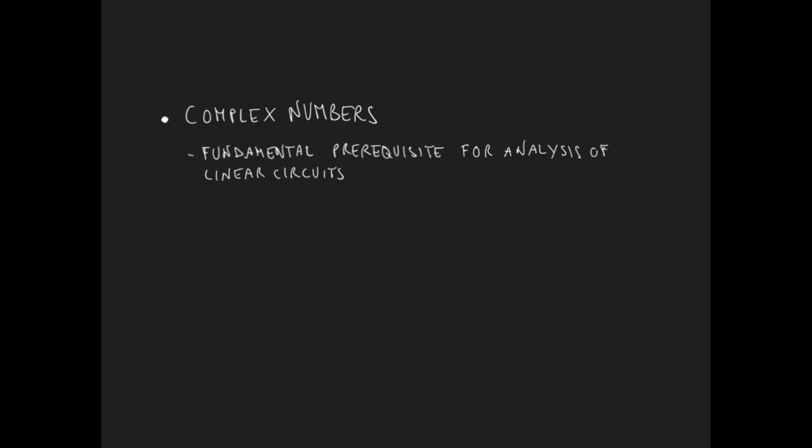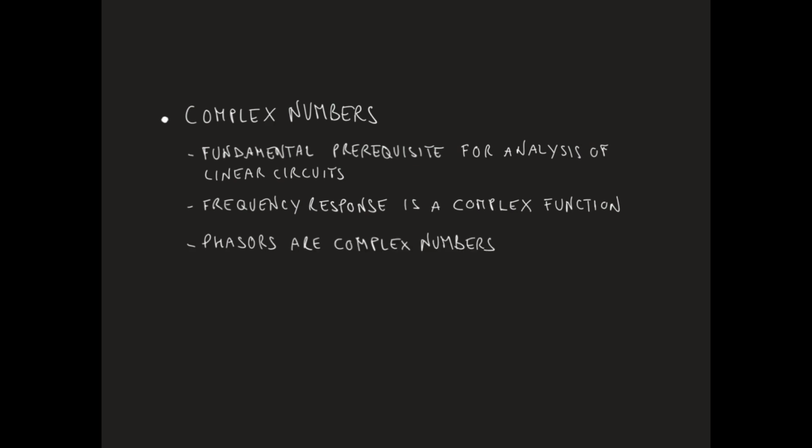The frequency response, which is used to describe the behavior of linear circuits, is a complex function of the angular frequency. Complex here has to be intended in its technical meaning, in the sense that the function itself takes values in the field of complex numbers. Phasors, that are used to manipulate signals in sinusoidal circuits, are themselves complex numbers. The frequency response of linear circuits and phasors will be defined and discussed in dedicated video lectures.